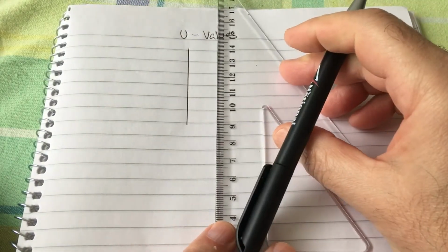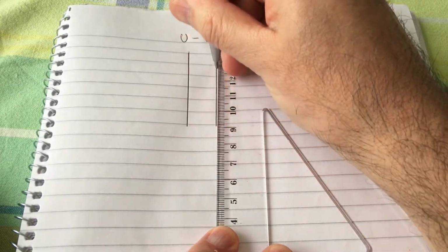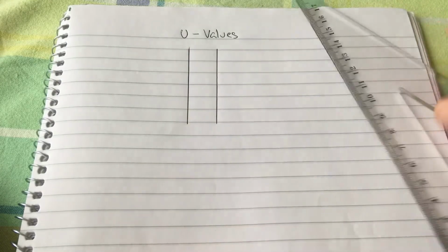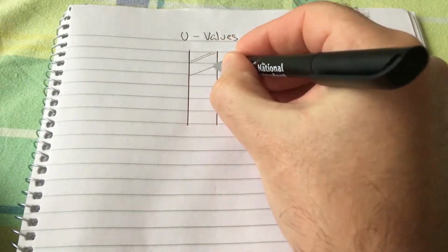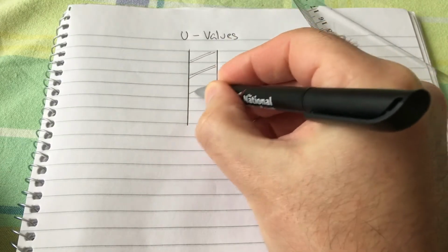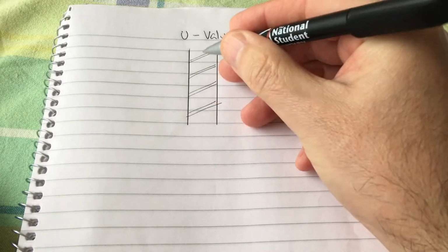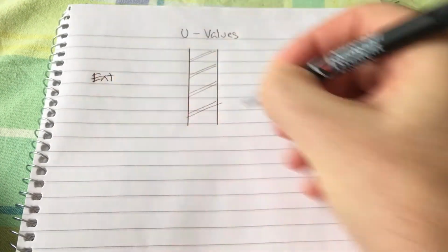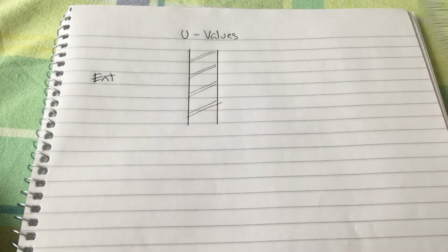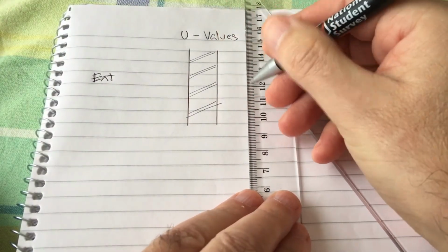Now, obviously, I'm not going to do the same wall that you have in the assignment. The wall I'm drawing is the wall you're more likely to find in a house built these days. Now, you can see here, that's the exterior wall, and you have studied drawings with Peter, and you know that to be the hatch pattern of a brick wall.